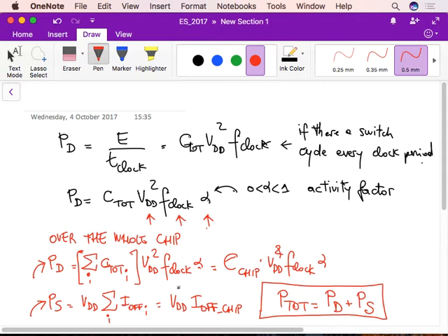It's not the only thing. There are different things that can be done. For example, I mentioned before the mobility increase. You see that mobility has no effect on the power consumption, but it can improve the performance because it can reduce the propagation delay. And so, historically, at some point, the only way to improve performance was to increase the mobility, and therefore, it has been done. And it's not something you can then change.